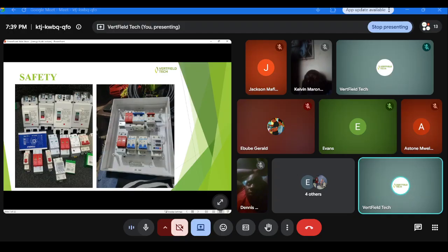Just like your fuse and your breaker, they protect against the same parameter, but they are not used at the same point. They are not used the same way. Your MCB and your MCCB protect against the same parameter, but they are not used for the same purposes. I hope it is very clear. While your MCCB is best used for another component, your MCB can be used for any of the solar components.